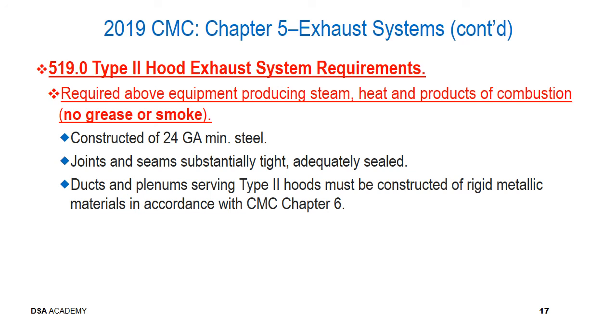Additionally, ducts and plenums that are serving Type 2 hoods are required to be constructed of rigid metallic materials and in compliance with Chapter 6 of the California Mechanical Code.